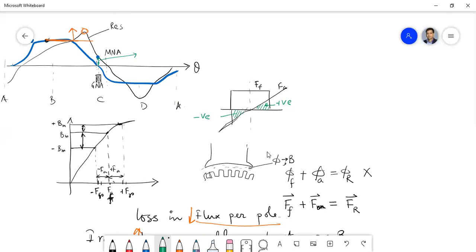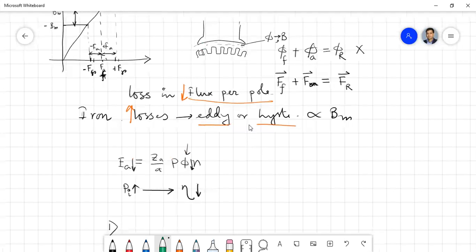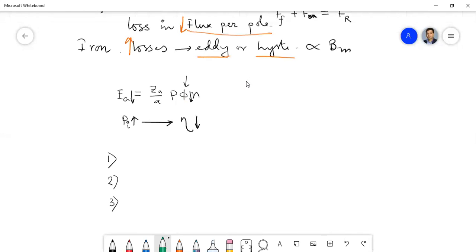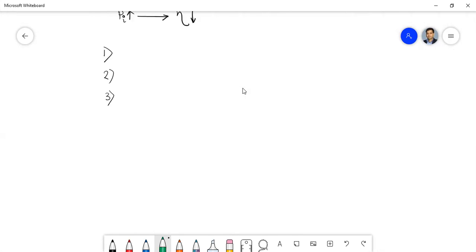That means there will be a possibility of voltage induced between two commutator segments going under commutation. Therefore, there is every possibility of puncturing the mica insulation and generation of arc, and this will give rise to sparking. So this is one reason. Another reason is different, that I will discuss under point 4.